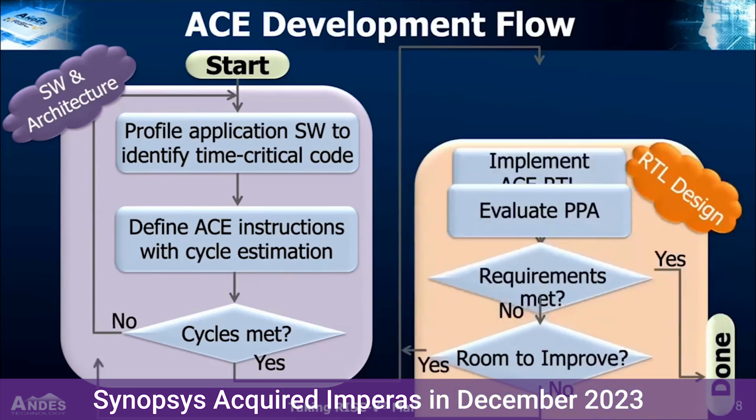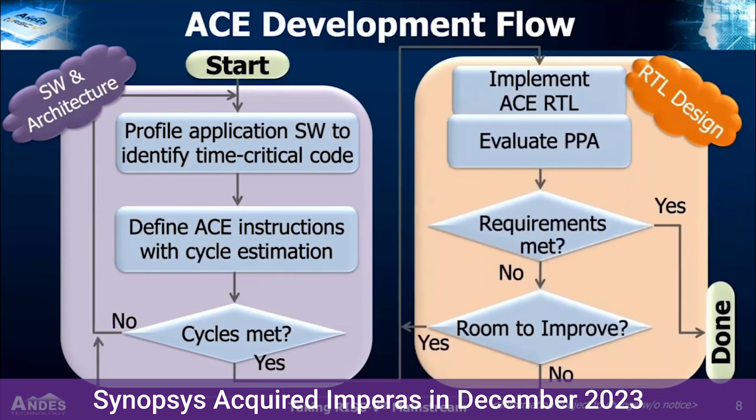Once the cycle target is met, you go to the RTL phase and implement your RTL. Again, evaluate PPA. Did it give me enough benefit for performance, cycles, or power? You wouldn't create instructions that made your performance worse, either in execution cycles, or power, or area. So it's an iterative routine. It's a standard, time-tested engineering development method. And by separating my golden model, my pure RISC-V code, versus the accelerated cycles simulator, and then the RTL, we get some extra benefits.